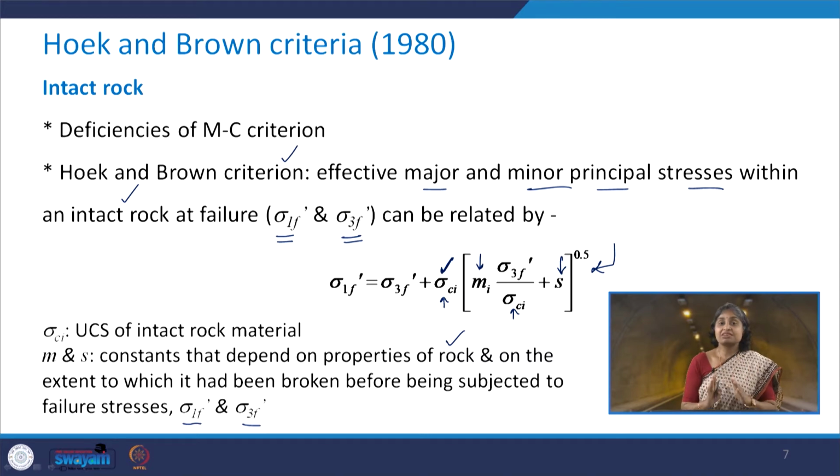No, it is not assigned the value of the UCS of the intact rock material, but is also treated as one of the fitting parameters to be found out from the triaxial test data which is conducted on the intact rock specimen.